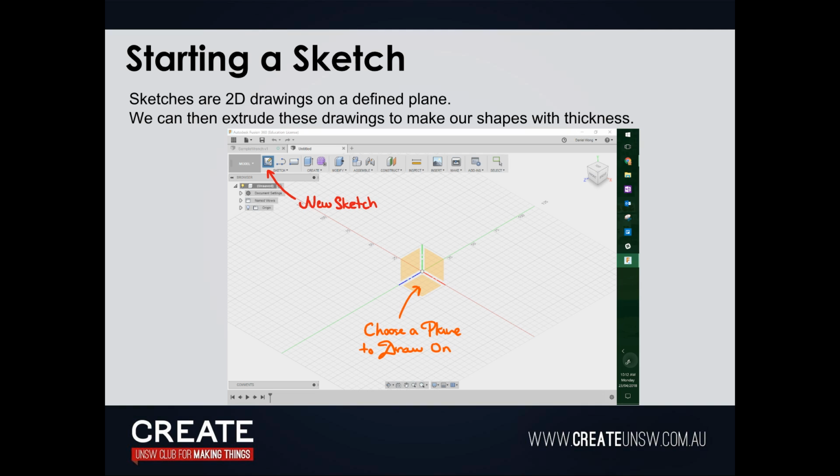Let me just exit out of that. So for example, if we want to sketch, create sketch, it'll let you select which plane you want to be on. Now, because it's 2D, it does make life a bit easier if you sketch on the top view. So just click on that and it'll automatically snap to that plane.